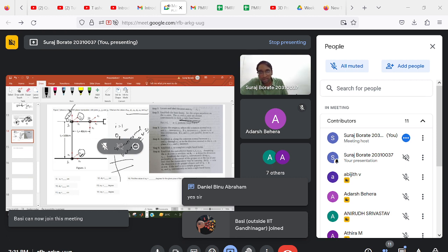So this is O1 and then X1 will be along the common normal. Now we have x and z, so we have to choose y such that this becomes a right angle triad. It should follow the right hand rule. X is up, z is into the plane, so y will be like this. Feel free to use your hands during the exam. So this is y, and all three are correct.